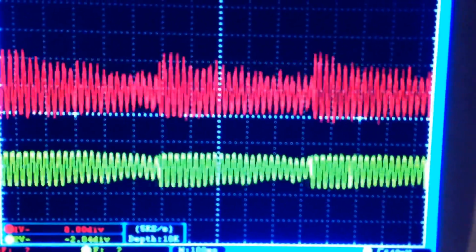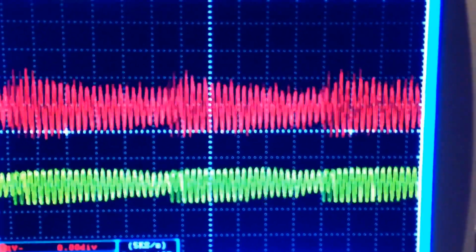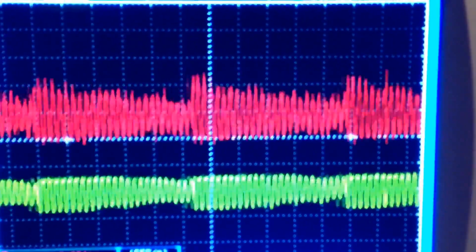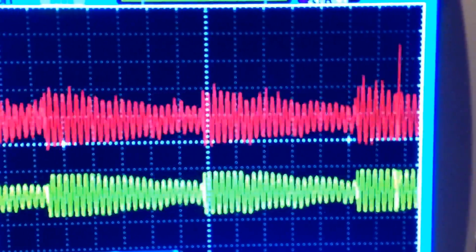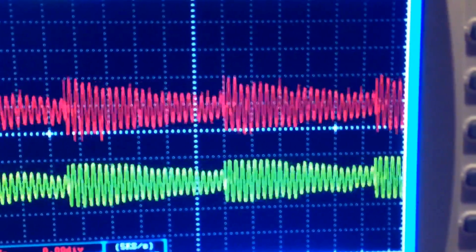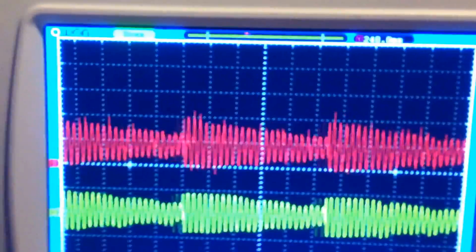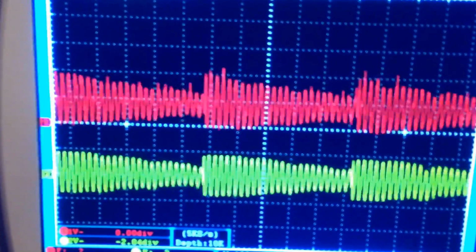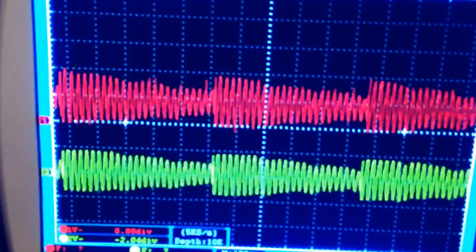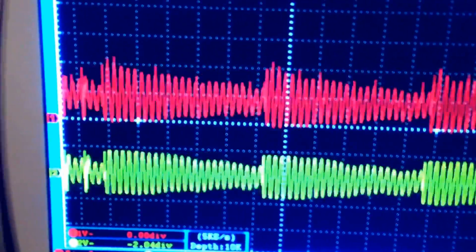So here's the first bit of sample rate reduction from 600 kilohertz to 60 kilohertz, which obviously won't do much. Gets rid of some of the noise. Part of that is a function of my function generator. It's pretty old and crappy, so there's a lot of ringing on the clock signal, which is fine. I have a ton of high frequency, high quality clock signal generators.